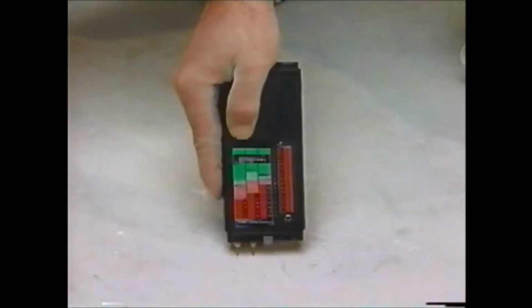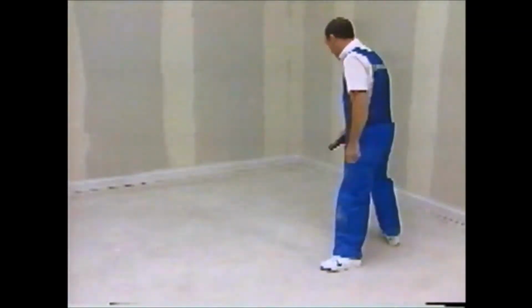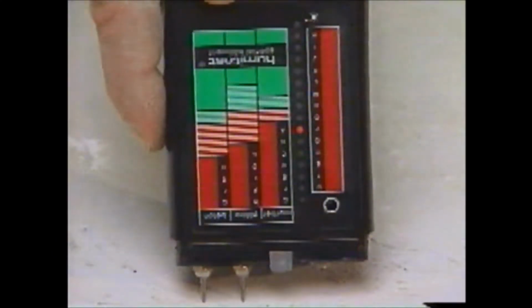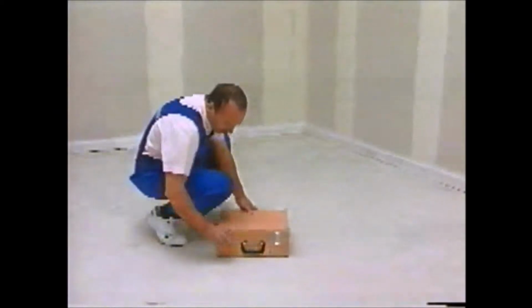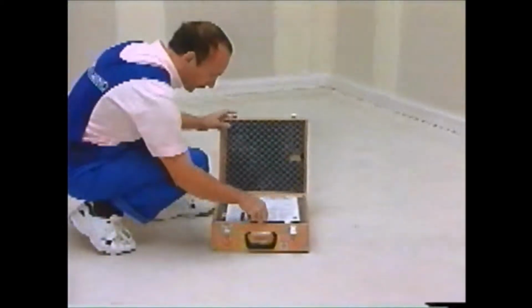Residual moisture shall be evaluated before installation by application of salt on the slab, by application of a sheet of PVC revealing condensation on the other side, or by the use of a moisture tester. The moisture content is measured using a CM dampness meter.